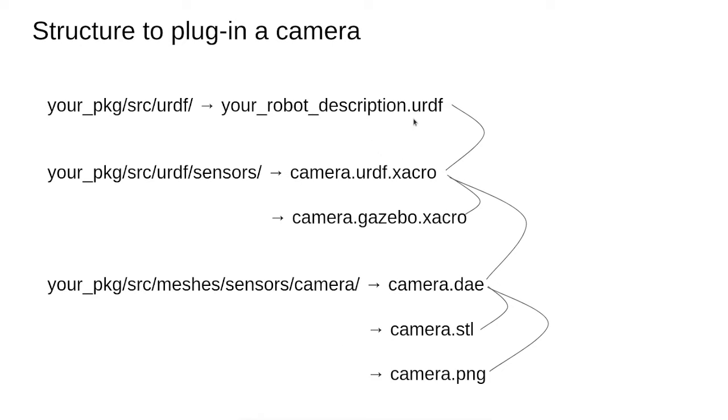In particular, the xacro file will be included, the xacro file will contain the gazebo file and the DAE file, and the DAE file will contain the STL and PNG files.